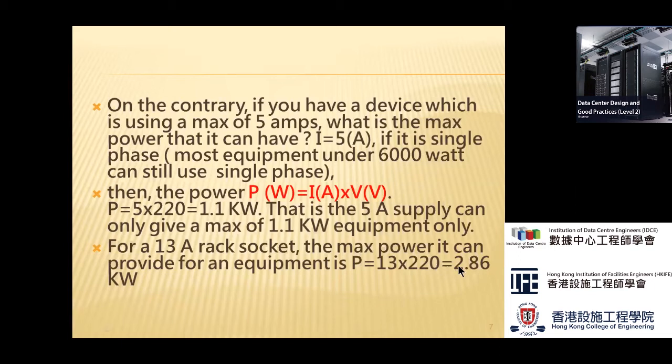If you have two bars inside the server rack, each with 5 sockets, for example, or 6 sockets, the maximum you can provide is two times this, which I think is 5.7 kilowatts only. But most racks, I think the normal racks would be 2 kilowatts, 4 kilowatts, or at the most 6 kilowatts. Or sometimes they can go up to 8, 10 and 20, and the largest one I've heard about is 20 kilowatts so far. Sometimes it's 40 kilowatts.